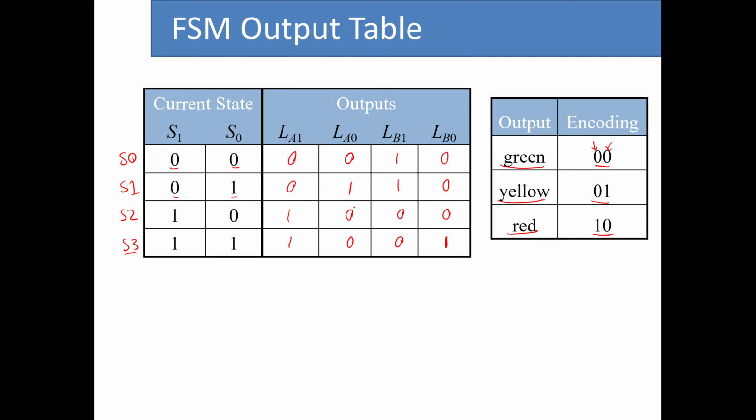So now if you look at this table, we don't have any abstract names, neither for the states nor for the outputs. And also to the left of this line, we have all the inputs for the output logic unit, and to the right we have all the outputs. Again, we can use sum of product, product of sum, K-maps to write the equations for the output logic unit. So again, going with the sum of product is the most straightforward way.